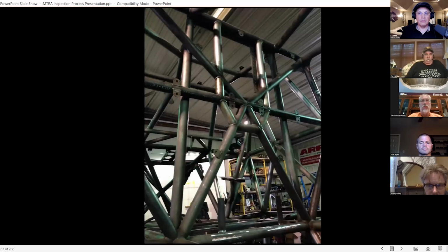Those bars behind the seat, in this example, those containment seats often attach in this zone up there by that U, right behind the driver's head. So seat belts fasten there, and the seat fastens there. Obviously that takes a big load. Somebody does a failed attempt at a backflip, and the truck lands directly upside down on its cab, all that load comes down there, pushing on all that stuff, and the seat is mounted there, so when it all bends together, that can cause some problems.